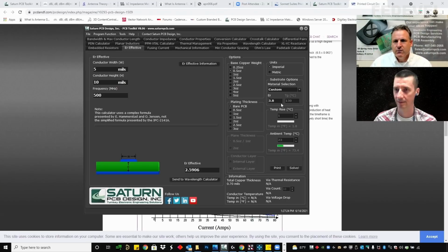And so you might think that, hey, my ER is 3.8. But at this geometry and this frequency, my effective dielectric constant, what's used for many of the impedance calculations and whatnot, is actually 2.59. So it's not 3.8, it's 2.59.